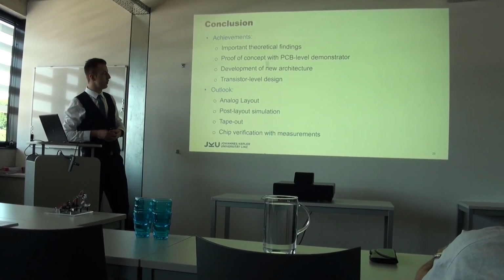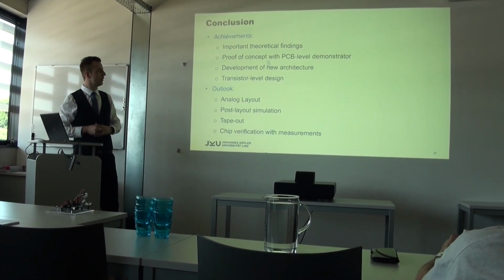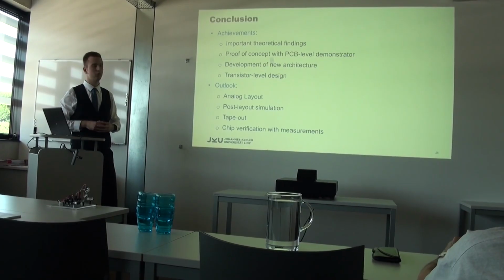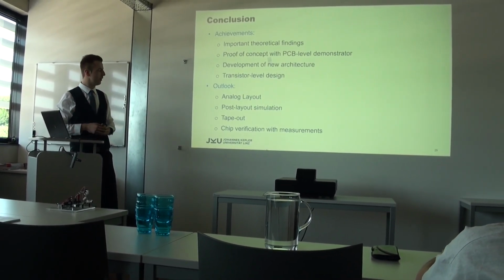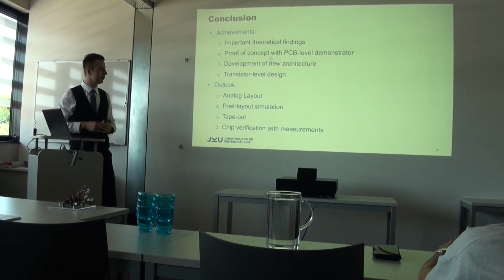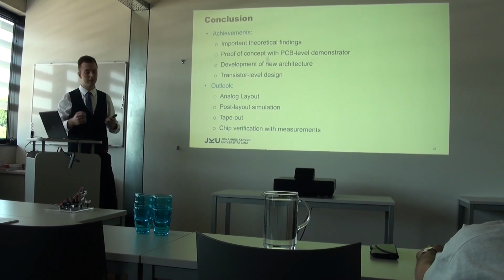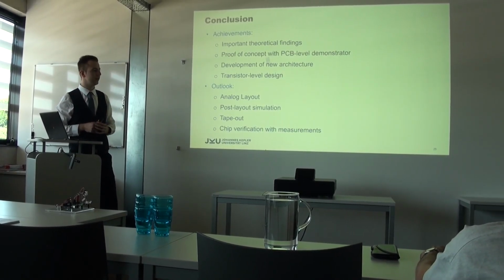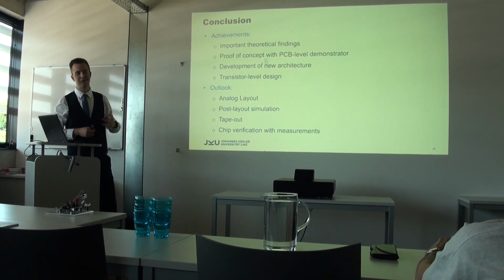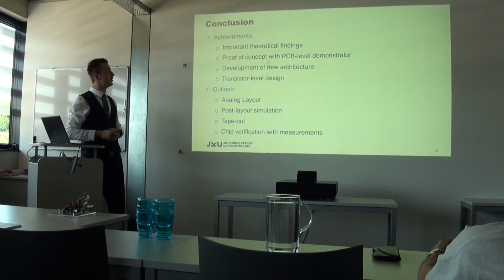Of course, we have digital layout, we don't have an analog layout yet, so I have to do this in the future. Of course, post-layout simulation with parasitic extraction, then the tape-out, and finally the chip should be verified with measurements, and hopefully someday we have a working chip which is producing spikes, which then can be used by the Institute for Signal Processing for further investigation.